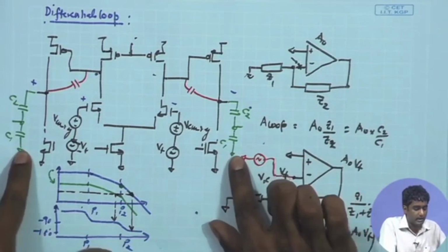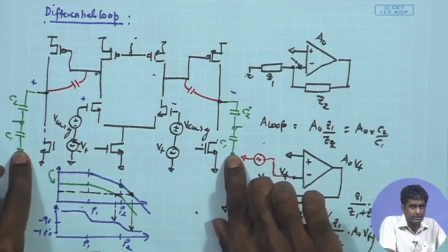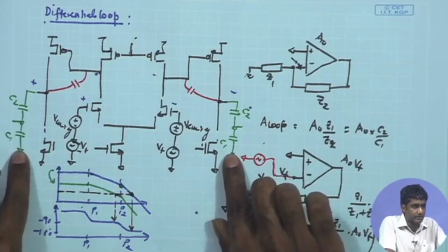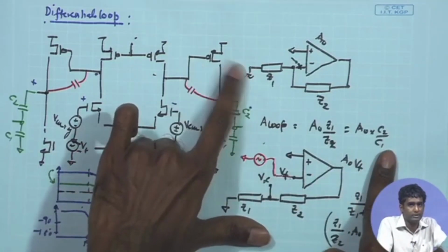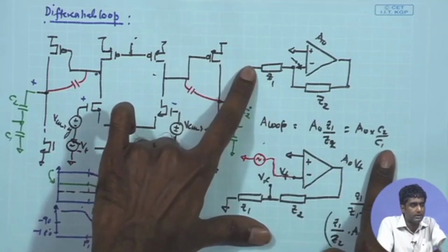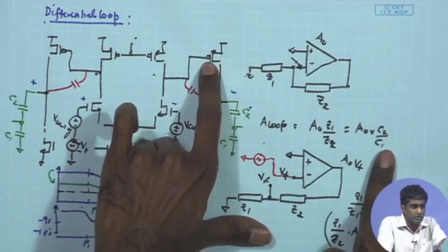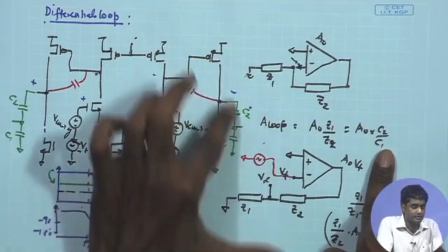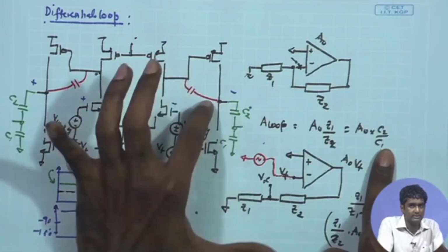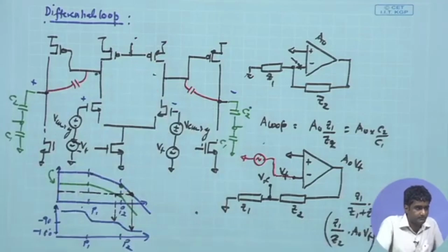So, it is not very necessary to put an appropriate DC bias over here, because this is the input point, right. In your actual circuit, this is the input point which is coming from the electrode, and we do not have control over the DC potential provided by the electrode. So, even if you put it to AC ground, it does not matter much, because this is not passing any DC. So, it is not influencing the DC bias of the amplifier in any way.